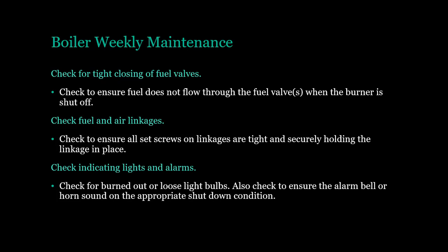Check indicating lights and alarms. Check for burned out or loose light bulbs. Also check to ensure the alarm bell or horn sounds on the appropriate shutdown condition.